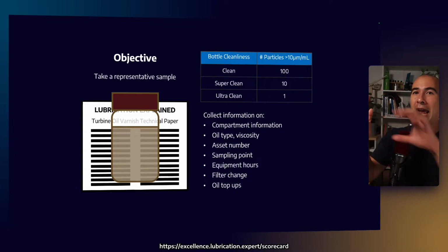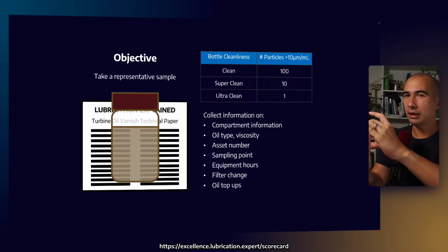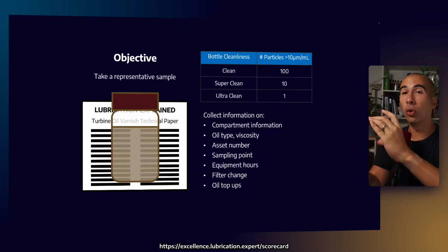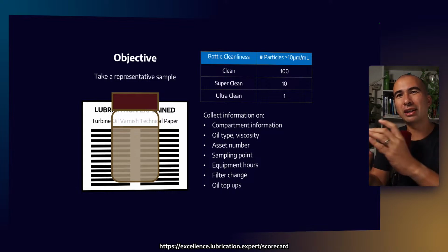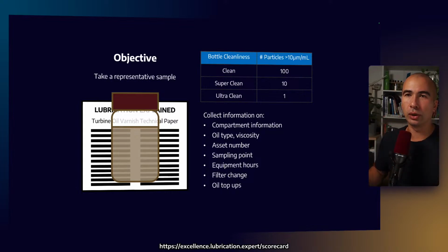But can we read a newspaper behind it is a pretty good indication of how much water is in the sample. So if it is clear enough to be able to read a paper behind it, then usually that is relatively low levels of water. Again, these are rules of thumb, which can then be verified by an actual lab analysis.